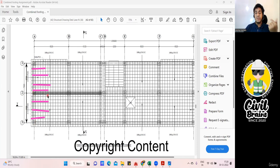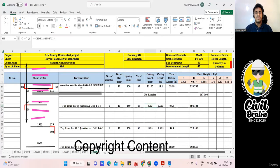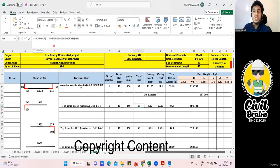Whatever answer you get, you divide by the spacing and plus how much? 2. 1 plus 1 will come for this span, 1 plus 1 will come for this panel. So 1 and 1 is 2, we have to do. Same calculation, I have done it here. That's it. So the number of bars, what did we do? Round up. Always remember to round up.